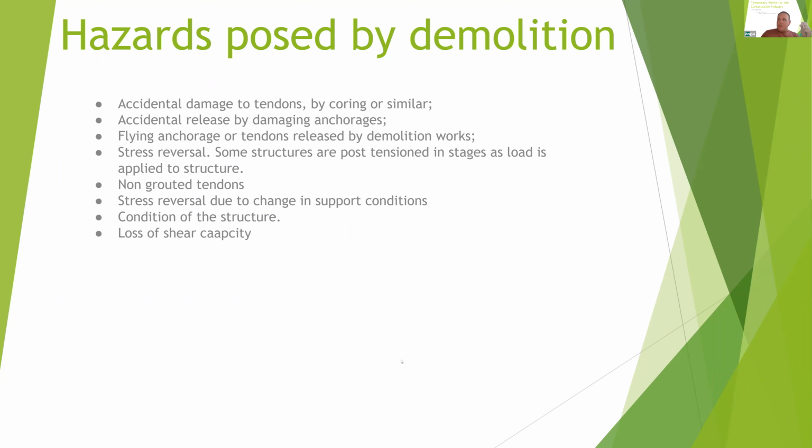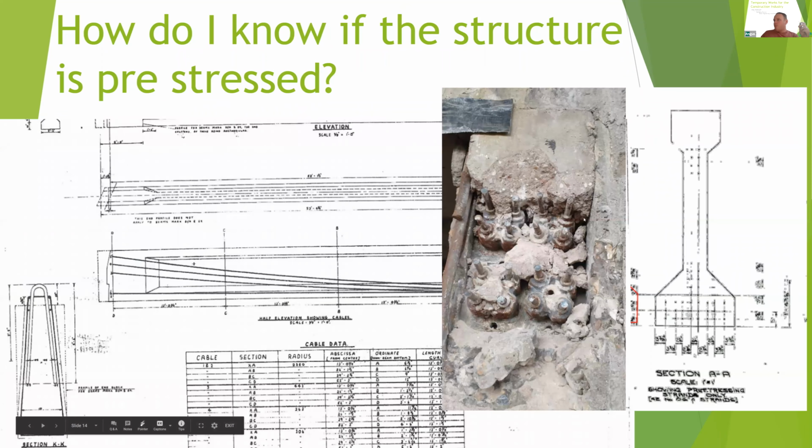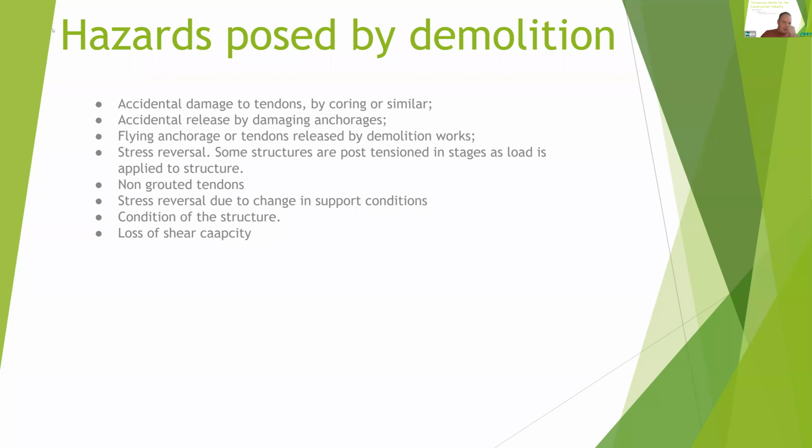If you damage the anchorages, so here, for instance, if you went at that anchorage point aggressively with a big breaker, you could well dislodge one of these collars and send that pinging around the site, which is a direct hazard to people.